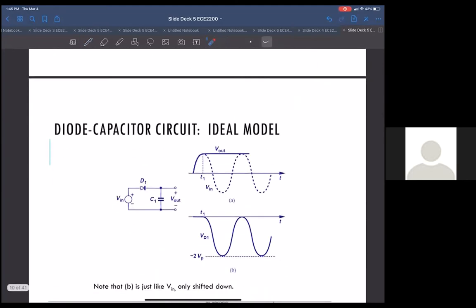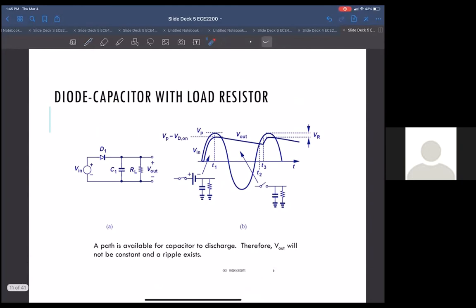Okay, and that has the effect of draining this capacitance. So instead of this thing staying flat, it starts discharging into my load. As it's charging the cell phone, the capacitor is getting discharged. So the waveform starts going down.